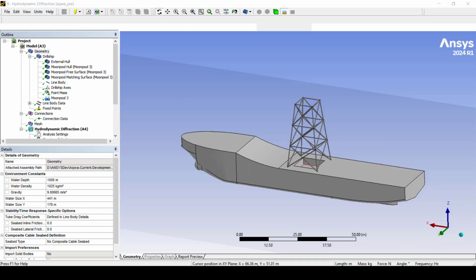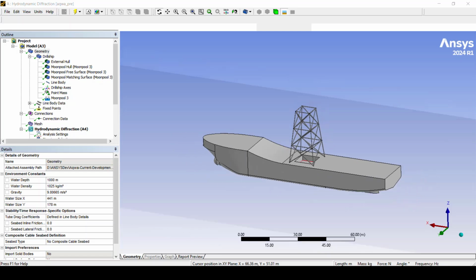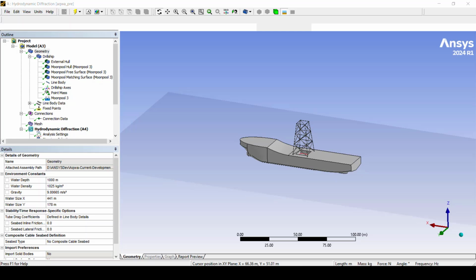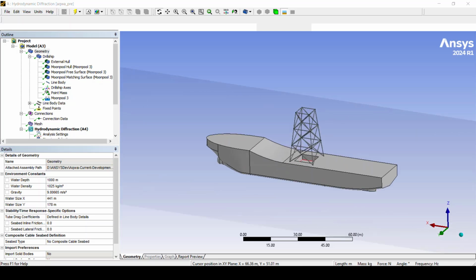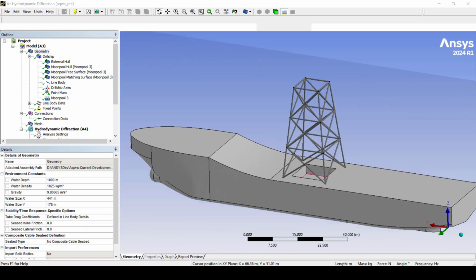The moonpool fluid region experiences reduced dynamic forces due to the external waves. However, this gives rise to large and complex water oscillation motions like sloshing or piston movements at some wave frequencies. In these cases, the water pressure acting on the moonpool surface must be carefully considered.